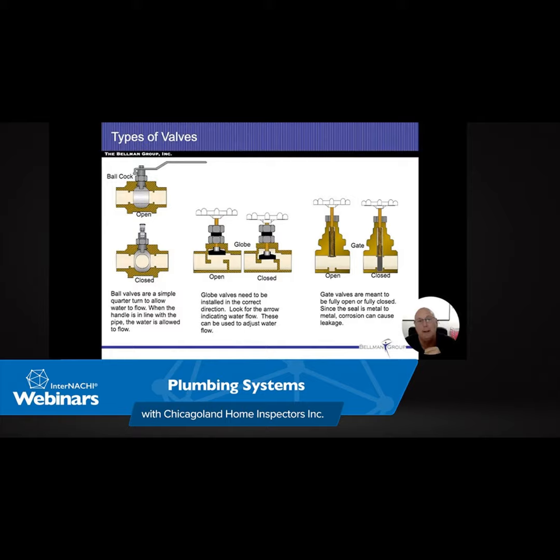So when we're dealing with functional flow, that's water coming in. When we're dealing with functional drainage, that's water going out. And it's a simple rule. Anything should be draining water as fast as it comes into it. So if I'm in a tub and I've got the water running from the spigot or the shower, and by the time I get to the end of my shower, I'm ankle deep in water, that's not functional drainage. All right. Now, if it fills up a little bit and then it holds it right there, that's still functional drainage, but it's most likely those lines are going to have to be cleaned.